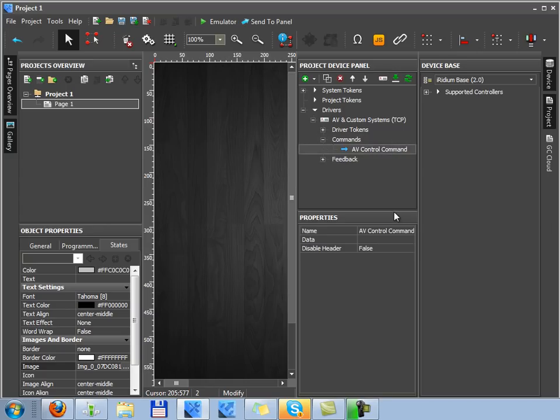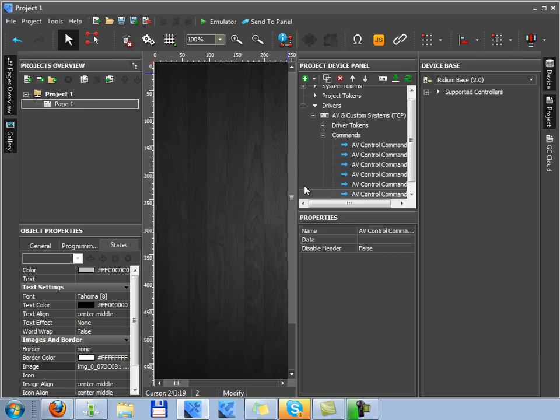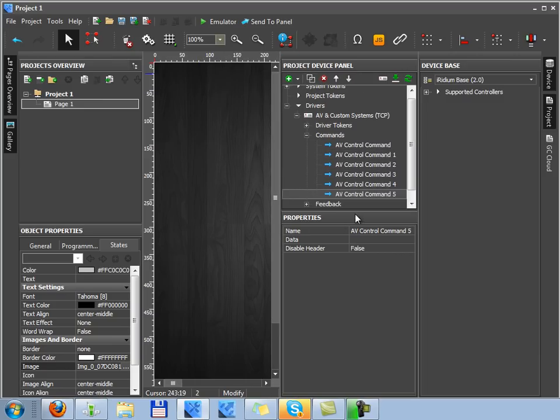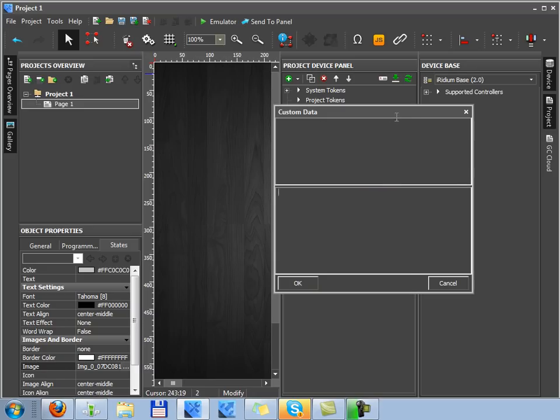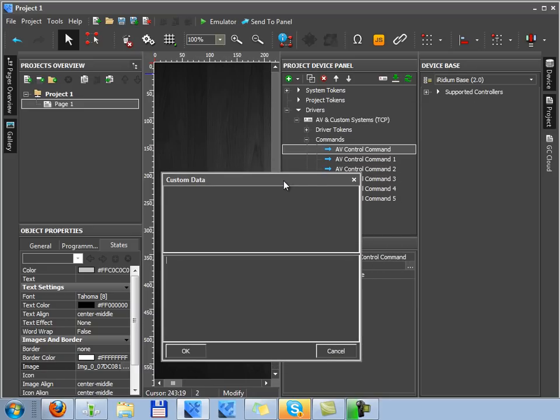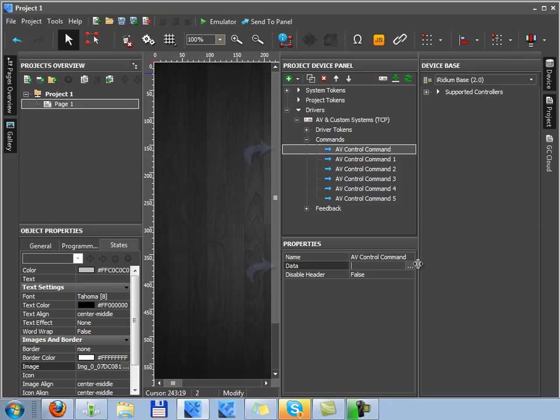Now let's stop on the commands tab, that is TCP request, which we can send to the equipment. There can be lots of commands. The number of them depends on the number of requests you want to send to the equipment. Input data is always a string of the ASCII format, which must be sent to the control equipment, and in some cases there can be data of the hex format. We'll stop on sending a data string to device via TCP.